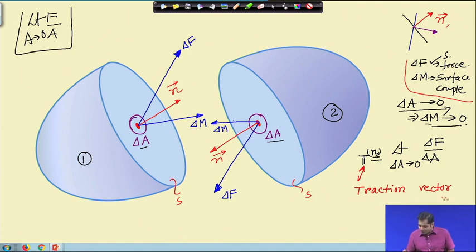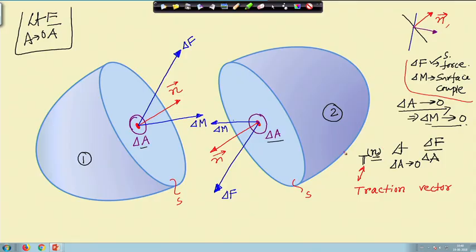So this is the traction vector. Dimension-wise, traction is also a force per unit area, like stress. When we write stress in tensor form, stress is always at a point and has stress components in 3 dimensions. But when we talk about traction, it is not just a point. Another important addition to the definition is the plane on which we are calculating the traction.